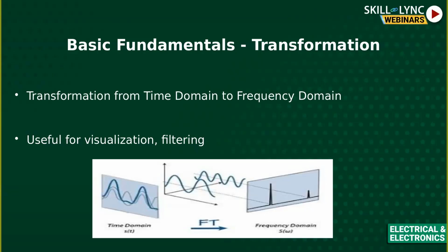So you can interpret those results based on frequency domain, and something which would not have been possible by just looking at this random signal in time domain. So by knowing this, then you could probably prevent those AC power lines from interfering with your device, or you could apply some kind of filtering in hardware or software inside your device. So it's quite useful here. And apart from this, this particular kind of transformation is also useful for visualization of your signal, to know what are the different kinds of signals your main signal is composed of. Okay, so that is another use case.